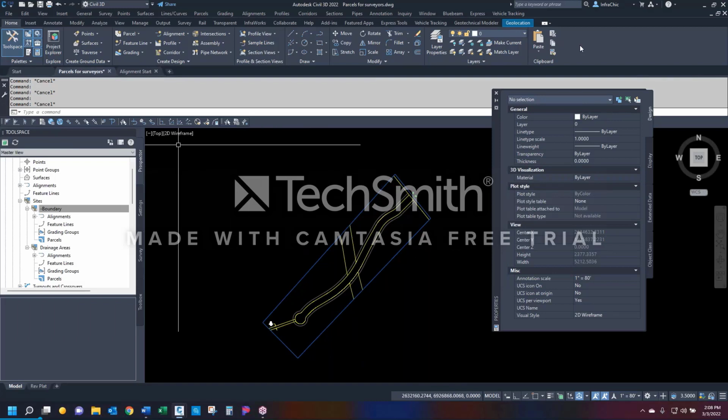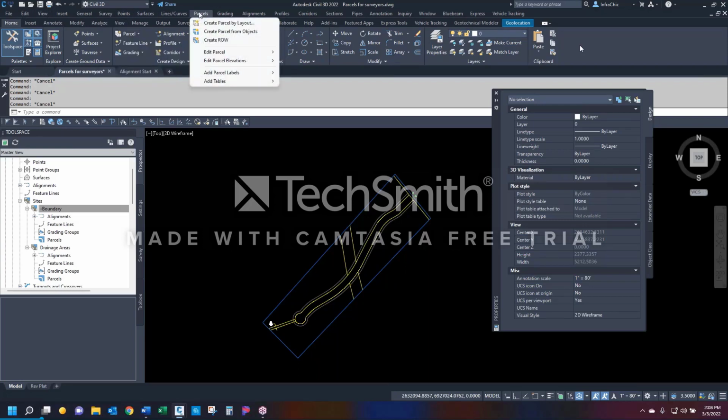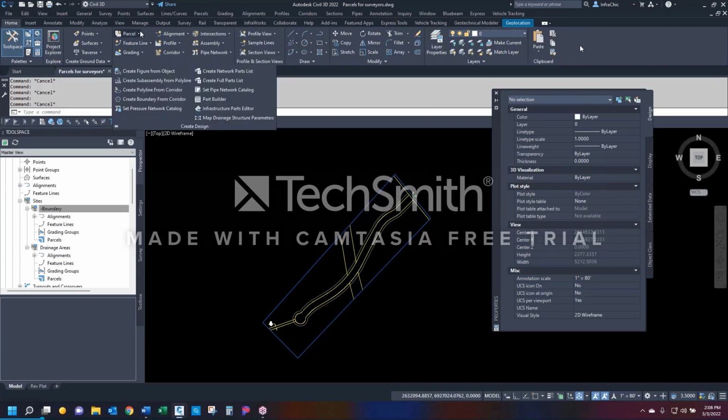I'm going to go up. I have five different ways to get to parcels. On the ribbon, it's on the Home tab, Create Design panel, and Parcel. Parcel creation tools: create parcels from objects and create right of way. If you have the menu pull down up here, it's under the Parcels pull down. Same tools: create by layout, create from objects, create right of way. If you don't have that, back on the ribbon, again under the Create Design panel, under the Parcel dropdown, grab Create Parcel from Objects.